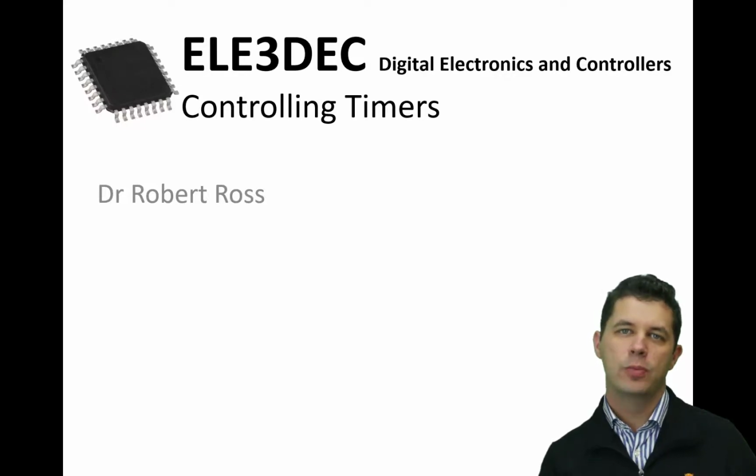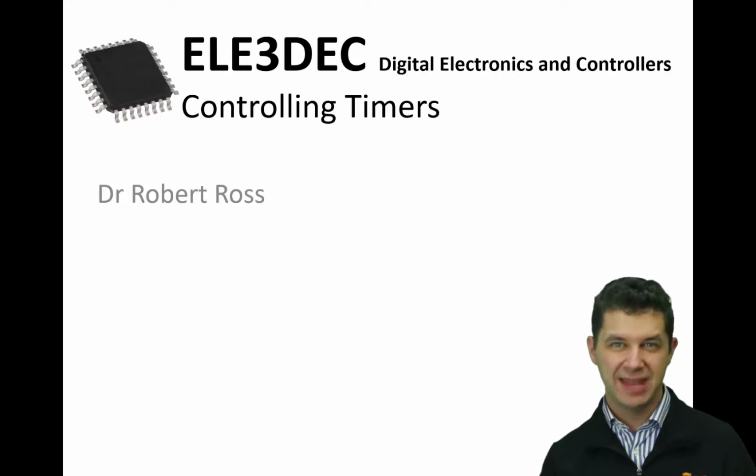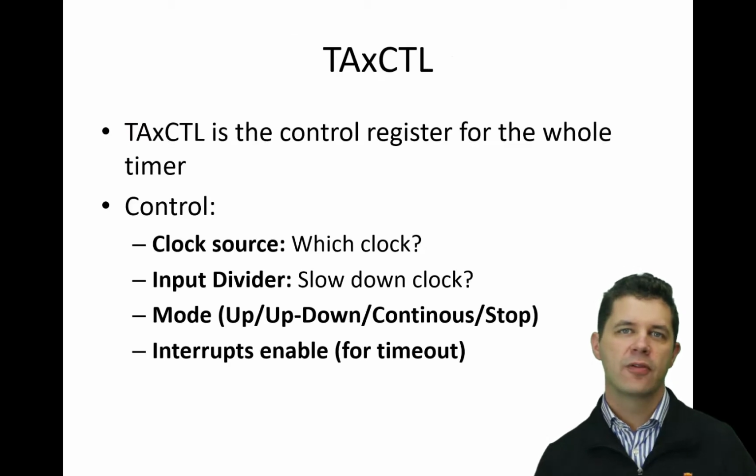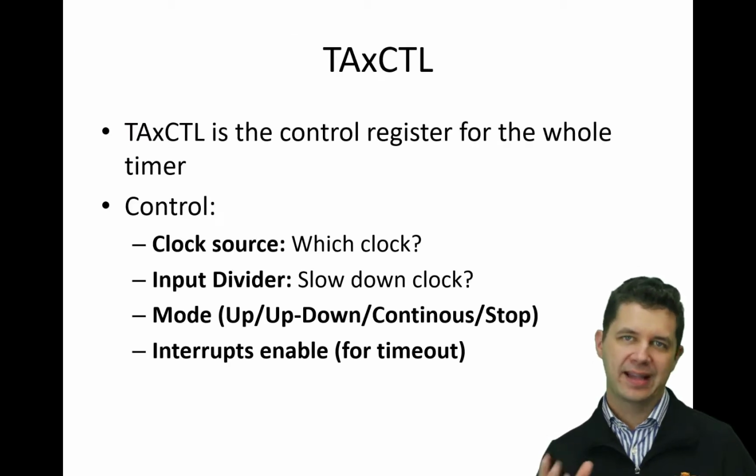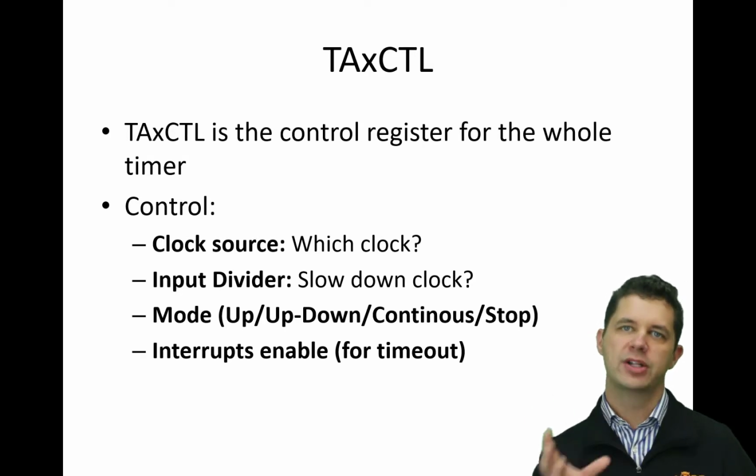In this video, we'll be talking about controlling timers, how we actually set them up and use them. So firstly, we've got the TAxCTL, TA0 or 1 CTL, the control register. And that's the control register for the whole timer.